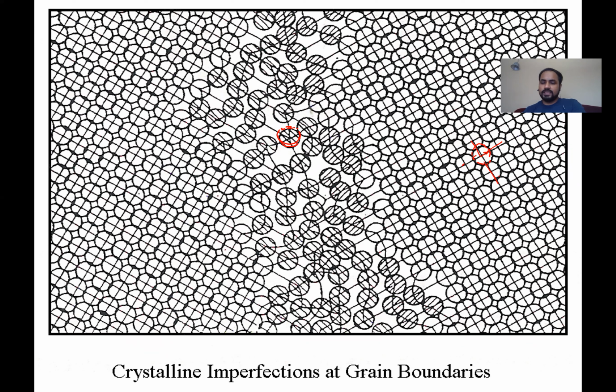If you do over etching, that means if the chemical is exposed for a longer time, then only the complete material reacts with the solution that you're using. So grain boundaries play a really important role, and they can define a lot of properties depending on if you want something really strong compared to, let's say, something ductile. Grain boundaries is something you should be playing with.